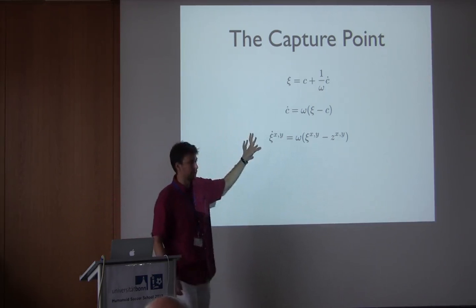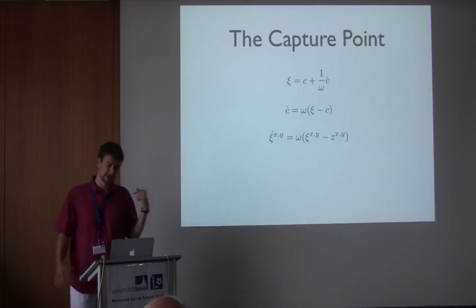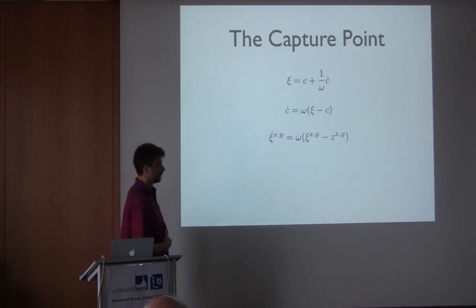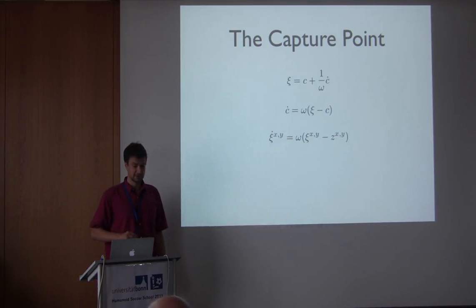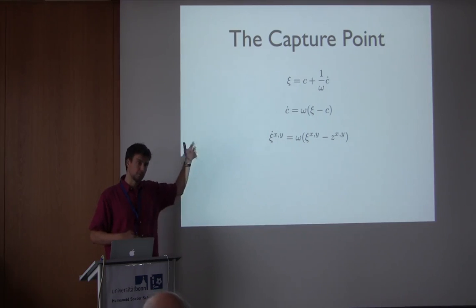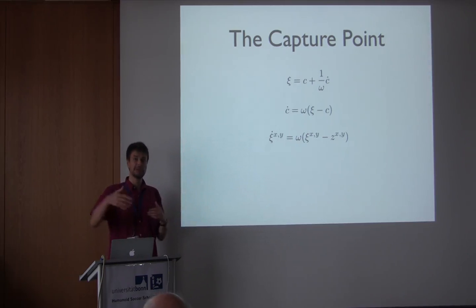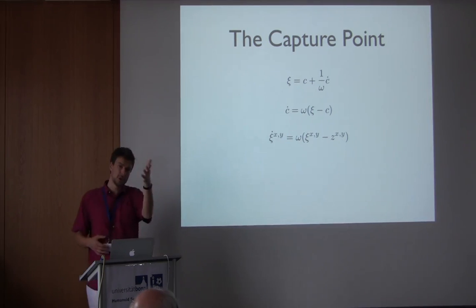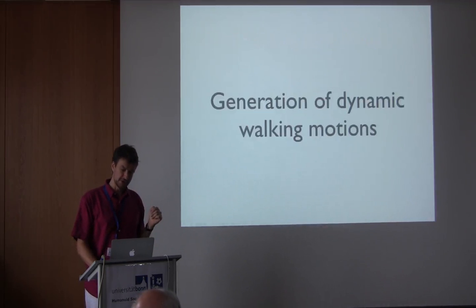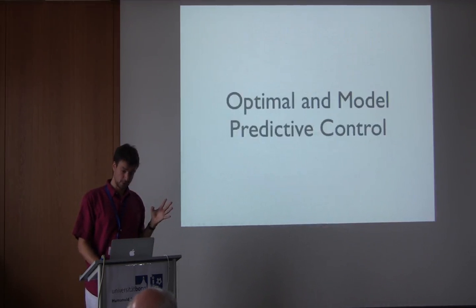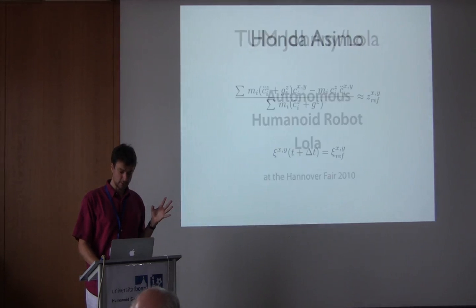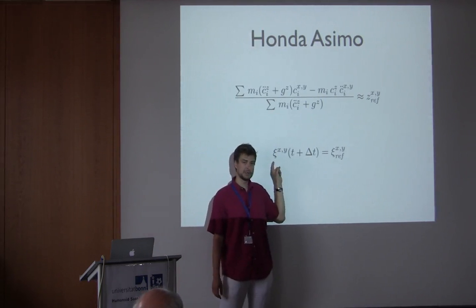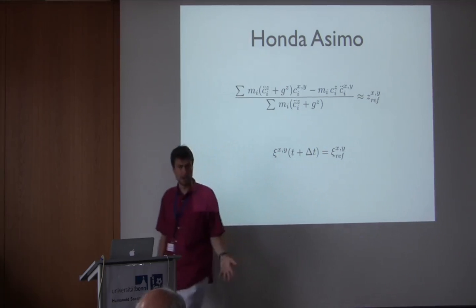So here I mentioned the capture point for stopping in 1 step. You have a recent paper by Pierre-Brice and all his colleagues, in two parts in the International Journal of Robotics Research, which is a fabulous paper, which computes the capture point for more complex models and then for many steps. So you have further developments of this idea, but not the one that you want. However, this is usually solved numerically. So, for example, in the Asimo scheme here, the capture point is decided to be put in some position.